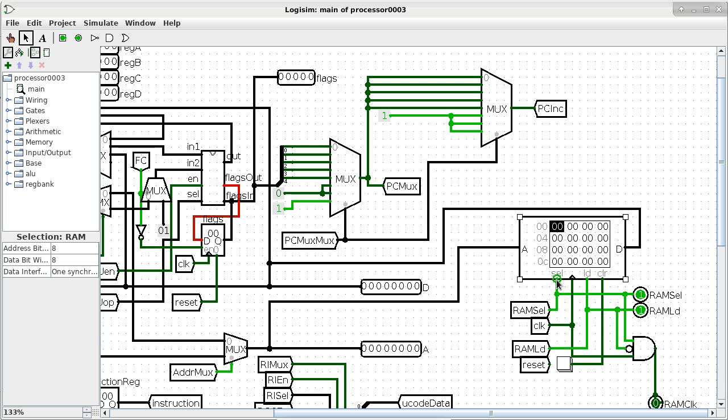It's level sensitive. The second one, which does not have any actual name, is only represented as a little triangle. That's our clock line. It is also analogous to the clock line of our D flip-flop. A rising edge means, let's go ahead and store whatever is presented at the D port to whatever the A port is specifying. The location is going to be specified by the A port.